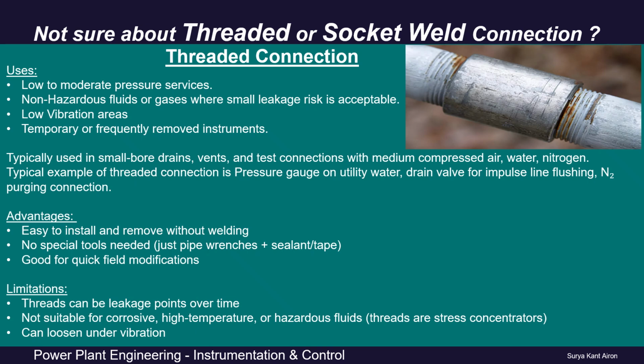So threaded connections are used where we have low to moderate pressure services, generally up to ASME class 600 and sometimes up to 900 for special cases.